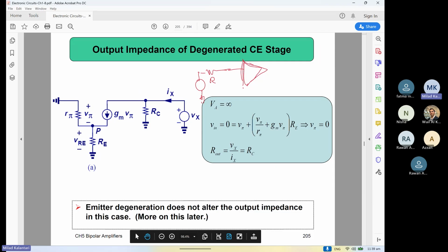If the amplifier impedance is low, then most of the generated voltage from the source is lost between these two, the internal resistor and the input impedance, right? So you don't want to lose the voltage from the input to the input of the next stage.